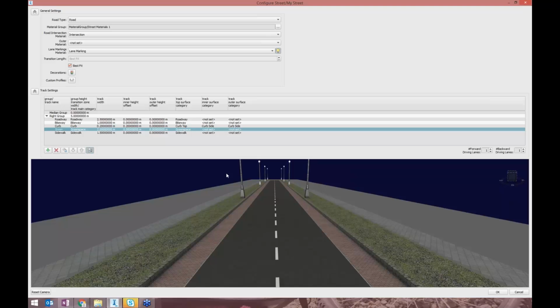You can do more here, by the way. Let me show you that maybe. You can add more aspects. You can even go down again, have another lane, go up again, and so on. That's what I told you, that you don't have to add geometry. If you want to have a complex road style, you just have to modify your style accordingly.